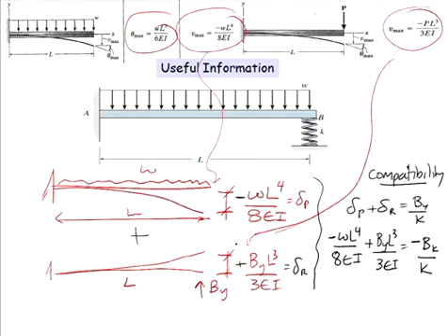Then you can say, you know how this sits in between the I-beams? What's the load on the I-beams if it just sits on the cross beams? Well, your load goes into the concrete, the concrete goes into the secondary beam, and from the secondary beam onwards.